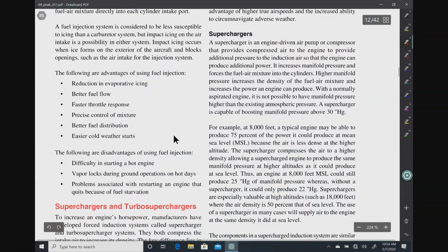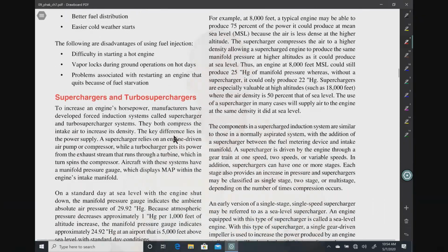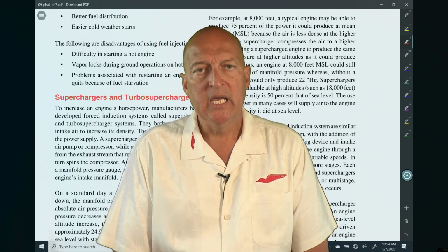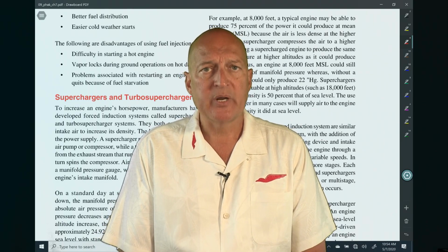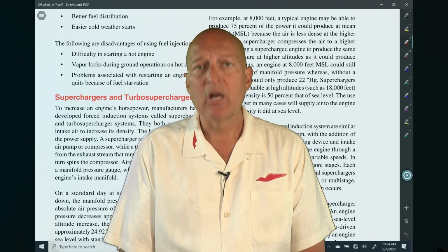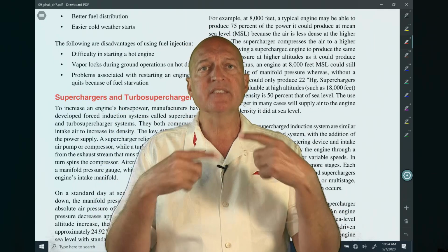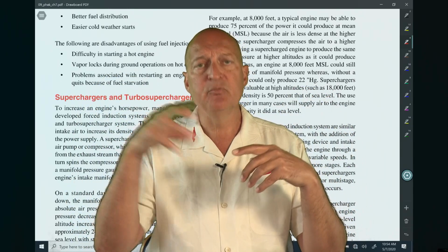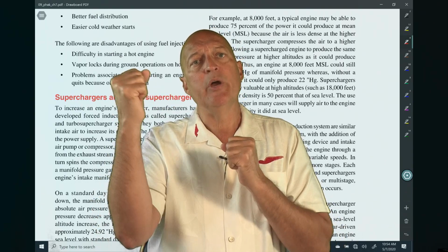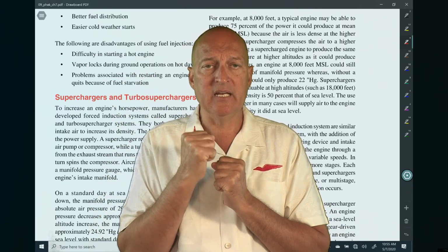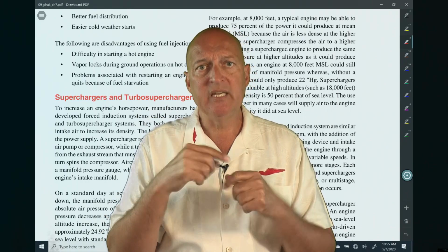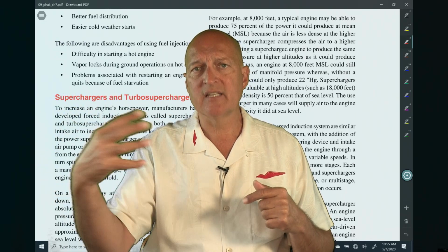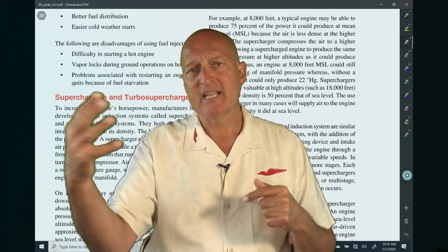Now, as we move through here, we can look at superchargers and turbochargers. What is a supercharger, turbocharger? Well, before we get into that, why would you need one? If you think about a normally aspirated engine, which is what we've been talking about before, that basically means that when the pistons move in and out of the cylinders, it creates a void, creates a vacuum, and it pulls air in. Well, that air can only get pulled in as much as that engine works, or you have a little bit of that ram air effect in those air inlets sometimes.